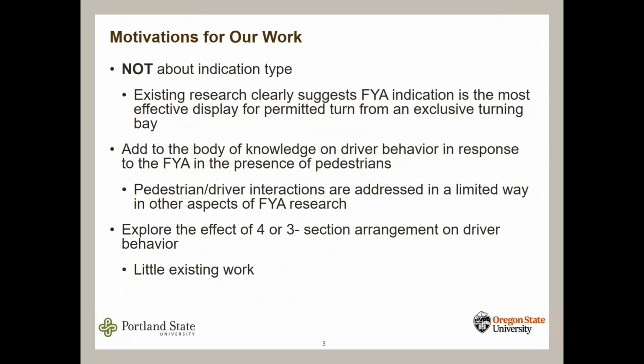The background and motivation for our work is that Oregon was an early adopter of the flashing yellow arrow for permissive left turns. So there's quite a bit of experience here using this indication. We weren't interested, when we did this work, in looking at alternatives for that display. Clearly the research has shown that the FYA is the superior indication for communicating permissive movements.